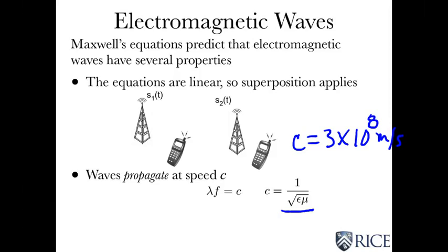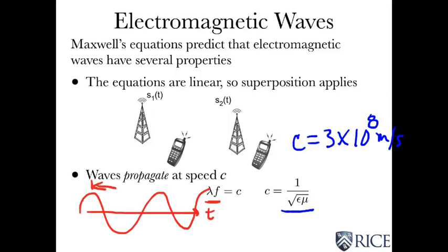Now there's another aspect of propagation that applies for sinusoids. So let's suppose I have a time axis and I have a sinusoid that's coming out of an antenna, so it's propagating. So this time difference is the period, and we know that's 1 over f from all we've already learned. However, I can also plot this as a function of space.